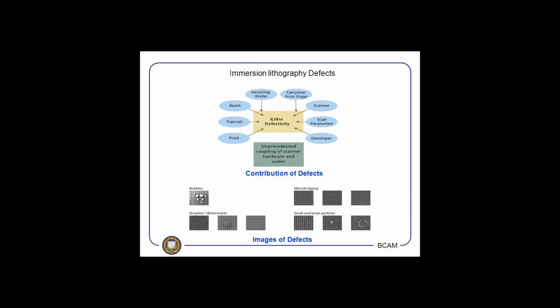AMD has also made preparations for advanced design for manufacturability, DFM, including layout regularity and double patterning at the 22 nanometers node, using immersion lithography. For the 32 nanometers node in 2009, Intel will begin using immersion lithography as well.